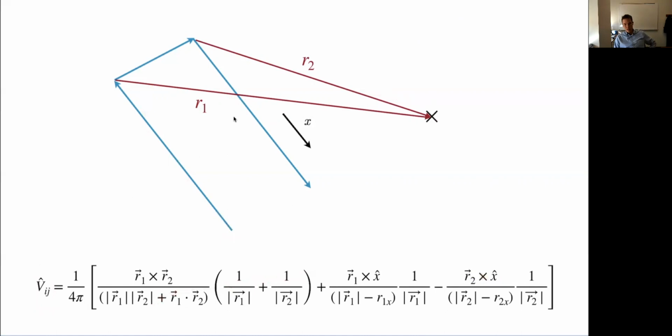This equation is a bit long, but it's because it's general, it's very robust. This can be anywhere. They could be on a wing and a winglet, a wing and a tail. They can be in any orientation, doesn't matter. This will work. If I have a planar wing, some of this will simplify. If I don't have anything in the z direction, I could simplify this a bit, but this is not too hard to implement in this form.